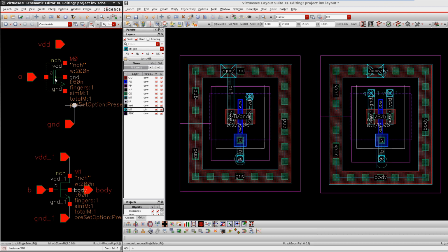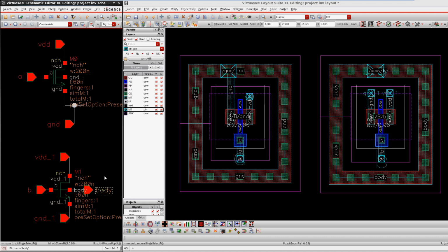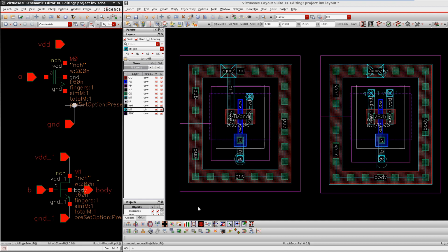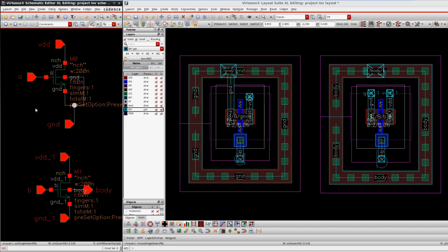See, when both N-channel MOSFETs are in the same circuit, in the same die, in the same wafer, but one MOSFET is connected to the ground signal and one MOSFET is getting the signal of body, right? Body, in the sense, is not a ground and not a power. Body is a totally different signal. This is not a ground signal. And now I have an equivalent layout here. Before checking everything, I'll show how the circuit diagram and the connections are given here.